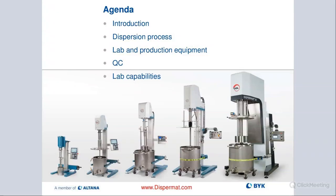So as you can already see here, just on the bottom of that slide, we basically offer all the different solutions from laboratory scale to pilot all the way up to manufacturing. And of course, most of you know, or those of you that don't, all of the equipment, the dispermats that we offer, have a modularity approach. That means that you can use them for dispersing, which is the first part of the process, and then also use them as media mills.